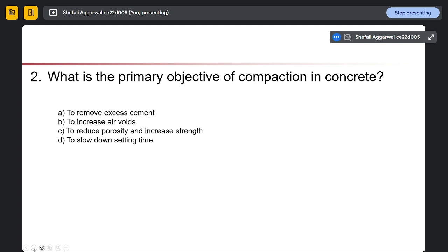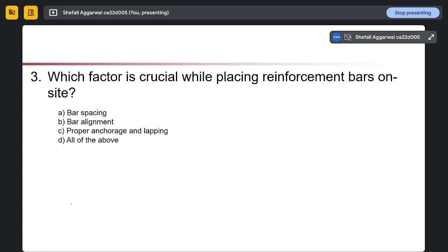Other than this, if we talk from the durability point of view, then we have the major issue of corrosion. Then we use corrosion inhibitors. These are also a type of chemical admixture, which reduce porosity and increase durability.